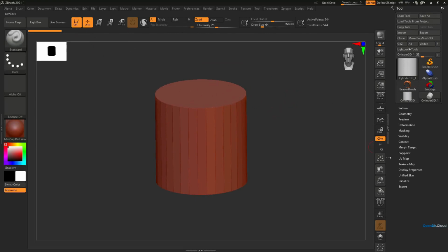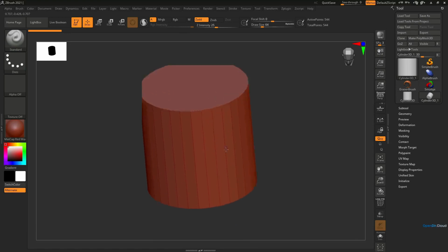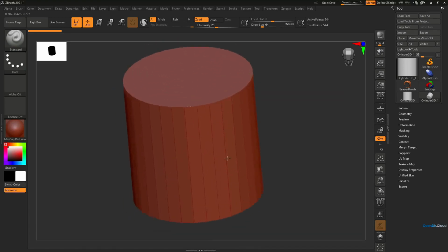You can control the camera with these buttons. Move, zoom, and rotate the camera. You can also rotate the camera by clicking the second mouse button anywhere on the screen. So you can also rotate the camera on an object. If you want to move it, press Alt and click the second mouse button, and if you want to zoom, press Alt and click the second mouse button, and then release Alt while holding the second mouse button.